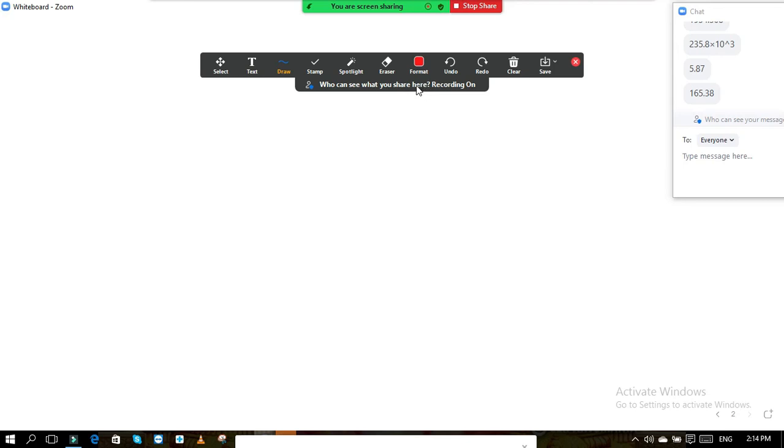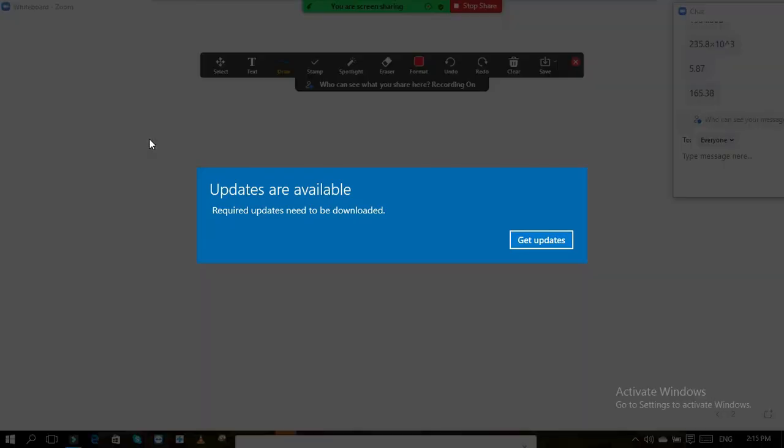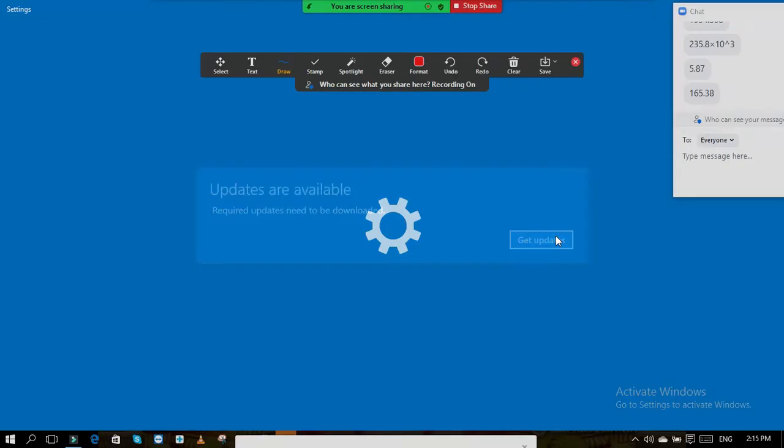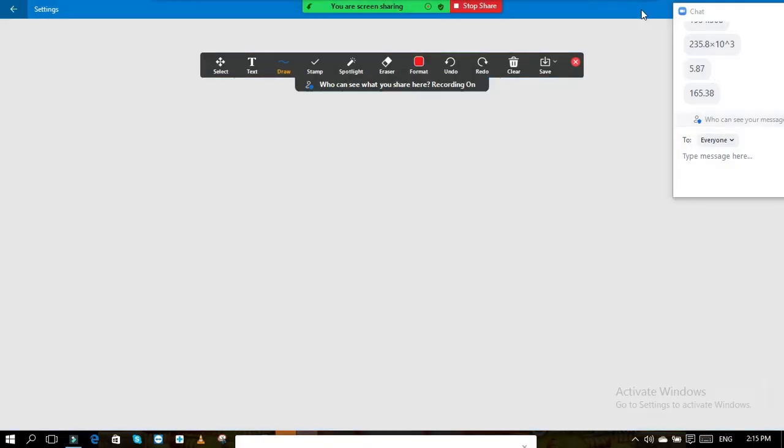So now the next thing is to calculate the moment of inertia of this I section. Okay, this moment of inertia will be required while calculating the resultant stresses. Right. So here we will not get the value of Z directly, BD square by 6. This is not a rectangular section. So to calculate the value of Z, we need to calculate the moment of inertia, then I by Y. If you do that, then only you will get the value of Z, that is section modulus.